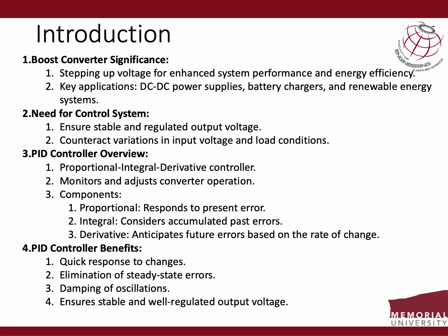Usually, if you require a power supply of, let's say, 20 volts, and you have a 12-volt supply, what do you do? This is where the boost converter comes in. You are able to design or implement a step-up converter to step this voltage up from your 12 volts to 20 volts. And this can be done by putting together some power electronic elements to be able to boost the voltage up.